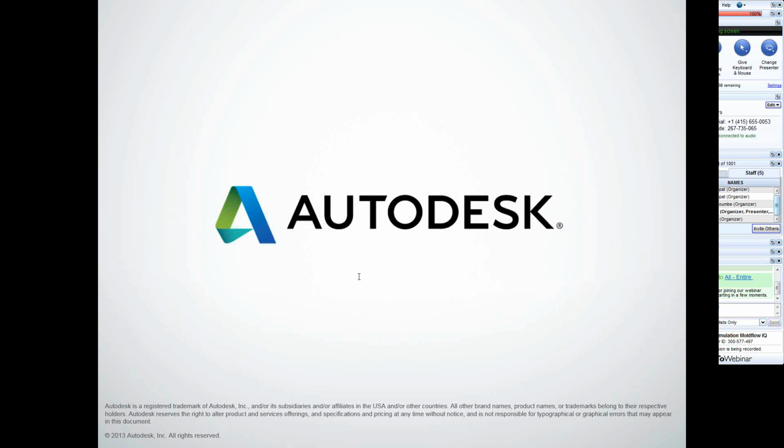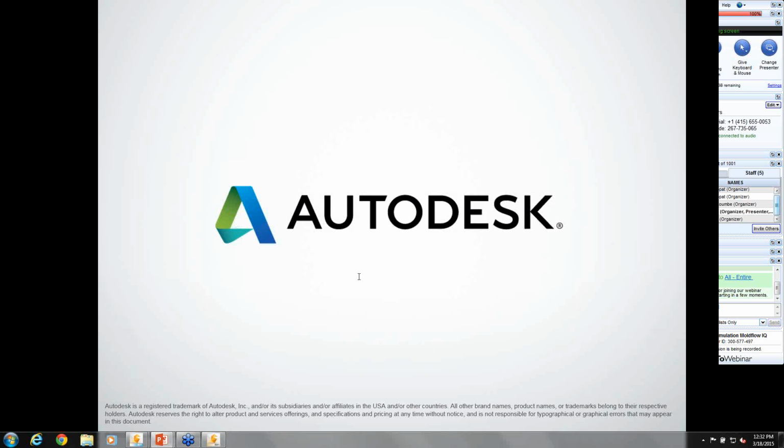I think the last question we have here is, can you tell me something about the contact diameter when I do not model the gate? Also, I do not see the difference if the part is an injection point and change the contact diameter. Okay, so you're basically asking about the contact diameter of the injection location. When you create a three-dimensional model, you have the opportunity to create what is known as a contact diameter, which basically is a shadowing of the diameter onto the elements of the part. What that does is it's basically being used for the initial shear of the plastic into the part. It's not really being used for much beyond that.